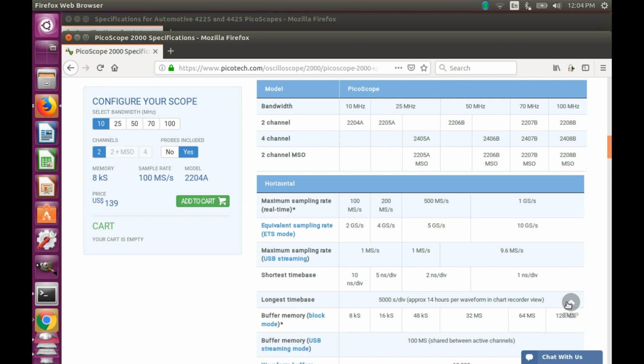The large buffer allows you to capture many packets, and then you can do serial decoding on those and maybe find something unusual. With a smaller buffer, you might be able to capture only a few packets, or even sometimes only half a packet. And so while you can look at the signal, maybe confirm that the transitions are good, that the integrity of the line is okay, you might not be able to do serial decoding with those.